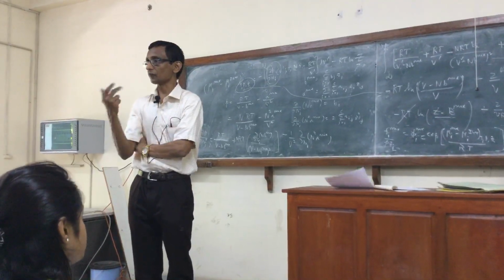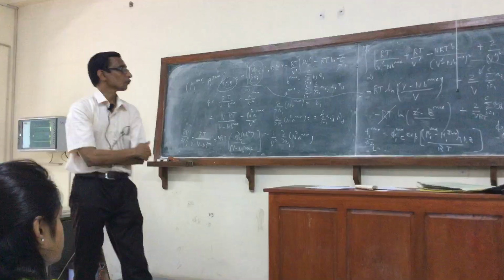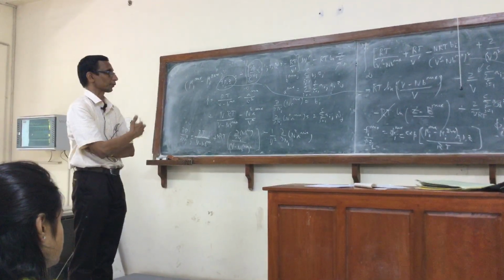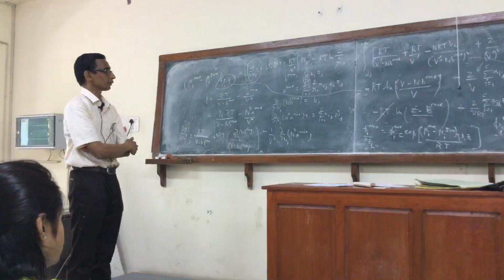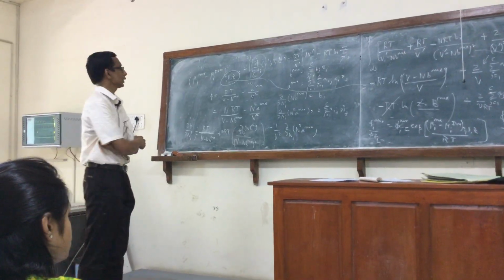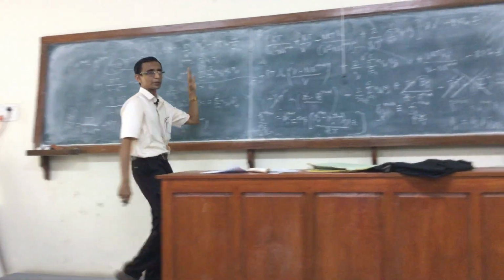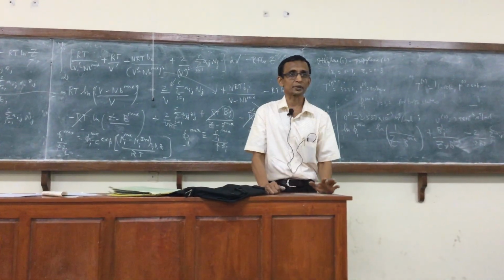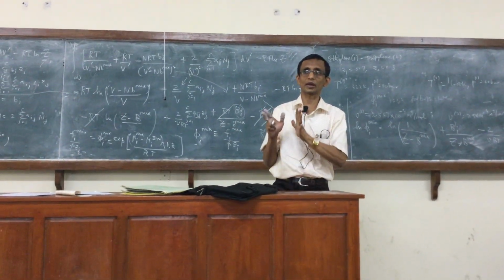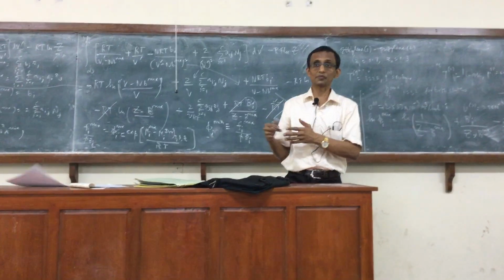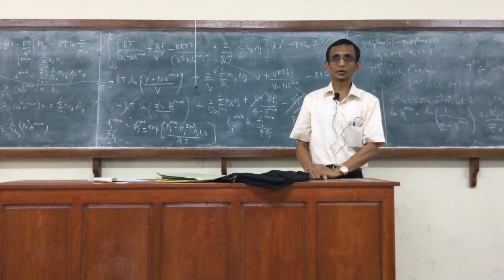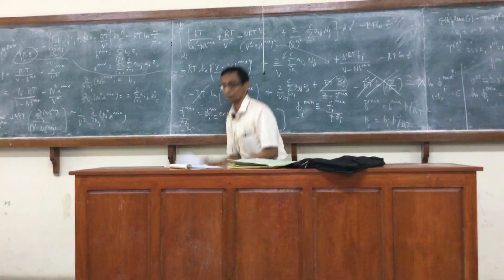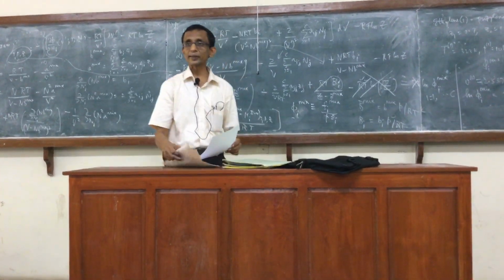So for the other equation of state, similar formulas must be available. You have the alpha also coming in for Peng-Robinson. It is a function of temperature. But here there is no derivative with respect to temperature, so in this formula there won't be too much complication. You just have a times alpha of T as it is. Right? It will be a function of temperature, so you have to calculate that for the temperature for the mixture also. Are there any questions?